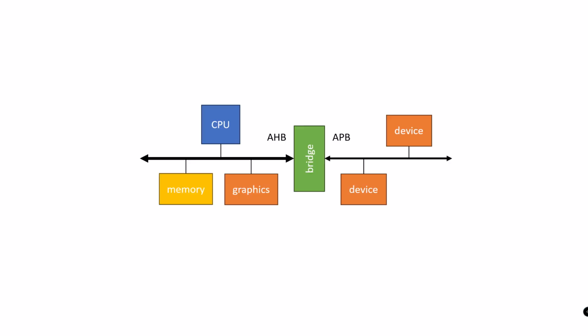Here's the results of simulating the handshake during operation. The ARM architecture provides an example of a system of 2 different buses connected by a bridge. The AMBA high-speed bus, or AHB, is designed for the CPU, memory, and other high-speed components. The AMBA peripheral bus, or APB, supports slower devices and costs less. The bridge mediates communication between the two.